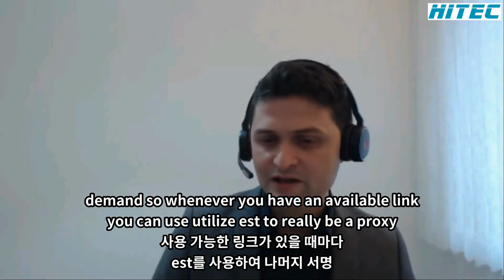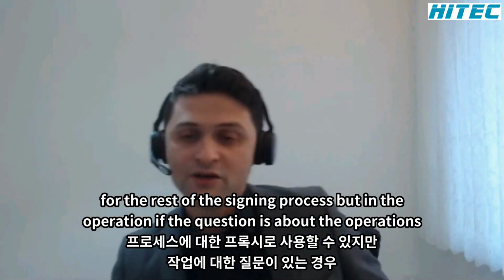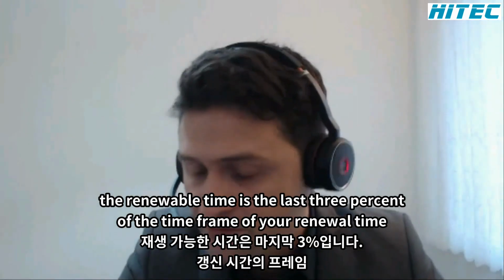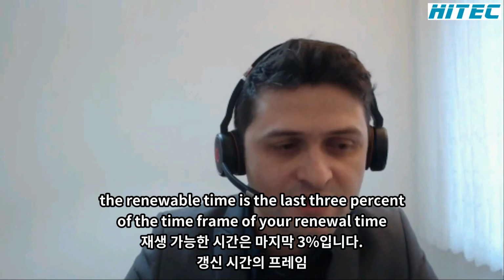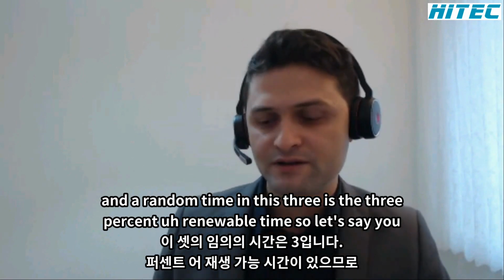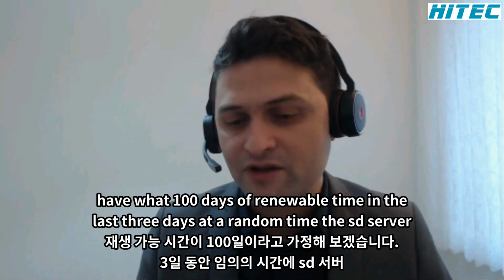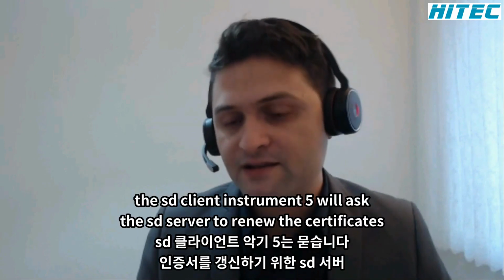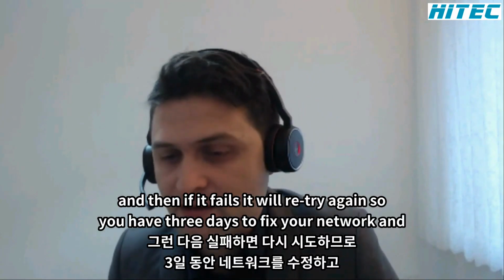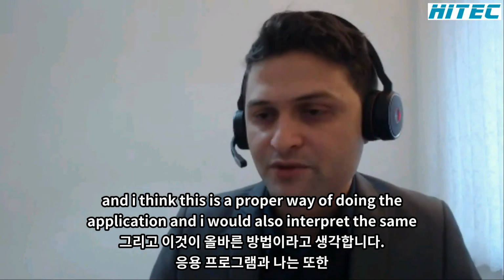So whenever you have an available link, you can utilize EST to really be a proxy for the rest of the signing process. But in operation, if the question is about operations, the renewal time is the last 3% of the time frame of your renewal time, at a random time. So let's say you have 100 days of renewal time. In the last 3 days, at a random time, the EST client in SIPROTEC 5 will ask the EST server to renew the certificates. And then, if it fails, it will retry again. So you have 3 days to fix your network,